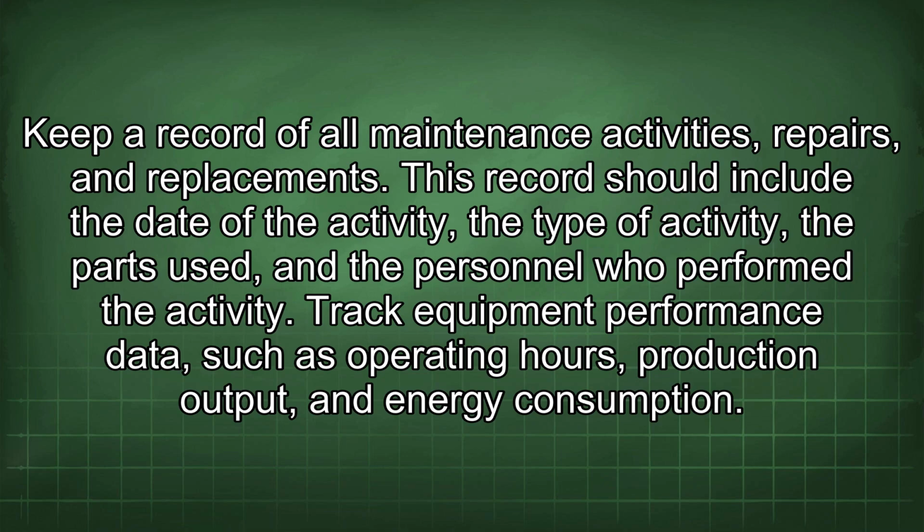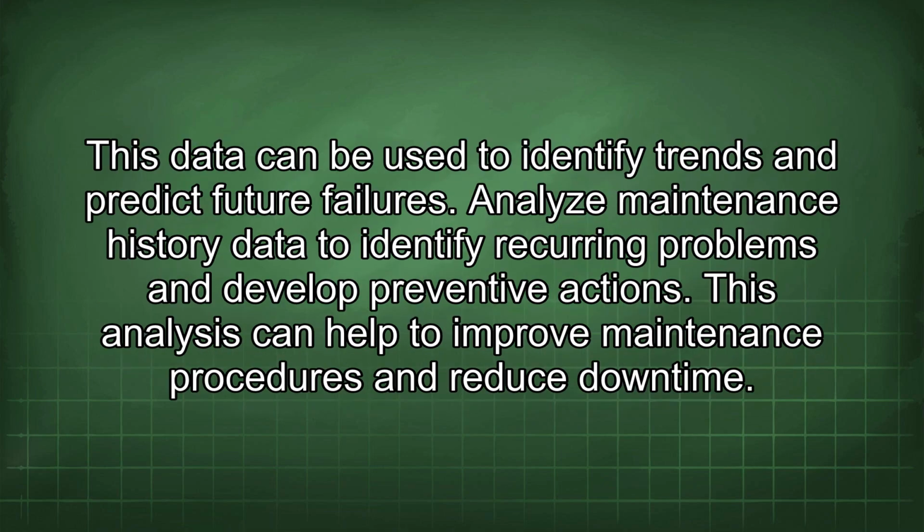Track equipment performance data, such as operating hours, production output, and energy consumption. This data can be used to identify trends and predict future failures. Analyze maintenance history data to identify recurring problems and develop preventive actions. This analysis can help to improve maintenance procedures and reduce downtime.